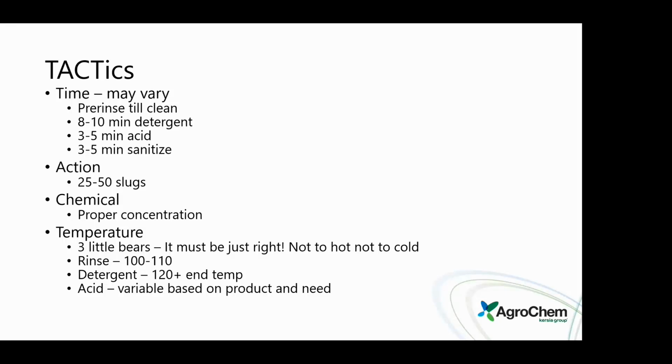Especially in that rinse cycle, when you've got things full of the fats and proteins that are in there with all the milk, we want to make sure we're in that rinse range temperature of 110 degrees, getting our system warmed up, helping to bring those temperatures to where they need to be when the weather's cold, but also at the right temperature to be pulling all of that out and getting a good clear rinse.